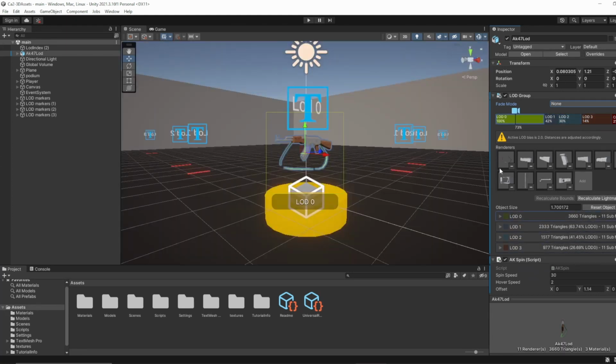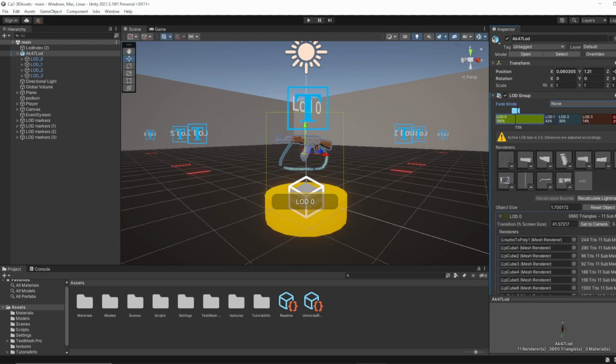And in order to load the different meshes, once you drag and drop the thing into the scene, if you look at the hierarchy, there's the different LOD groups that are here. So you can simply drop it in, and that's it. It just throws them all in, and this is now the current LOD group. I've just dragged the different ones to the corresponding ones like that.